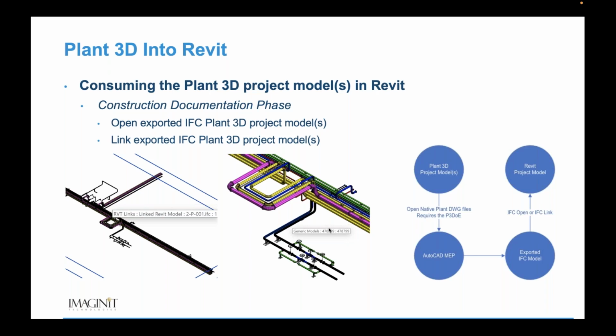This is probably one of the methodologies that I would use at that very last stage of construction document development, because I don't want to have to do it multiple times, preferably. And by having a separate model here, now I have two Revit models that I've got linked together with that information in it. Or, I'm trying to get this model information into another Revit model, which is not an easy thing to do. I know I've talked to some clients that have some other workflows with similarities to this that they've used before, and there may be some advantages in some of the processes they use over what I'm promoting here.